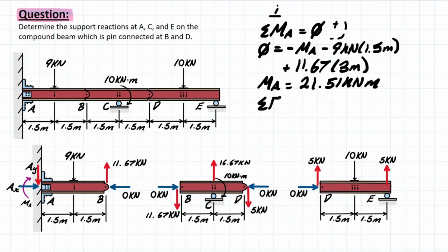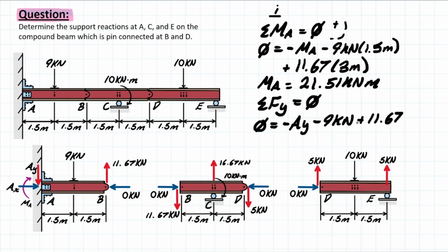And very simple stuff, guys. Summation of forces at Y. Taking that equation and figuring out what that AY is. So first we have negative AY as we've drawn it, the negative 9 kilonewton from the external force, sorry, and the reaction at B, which is positive 11.67, leaving you with your final unknown for this problem, 2.67 kilonewtons for AY. AX is going to equal 0. And you can plug this into your drawing for a nice, clean little picture for the end of this problem.